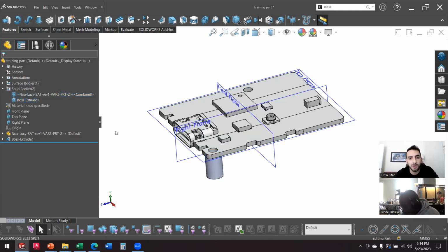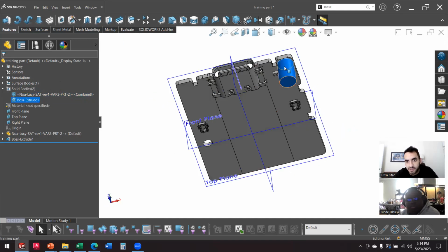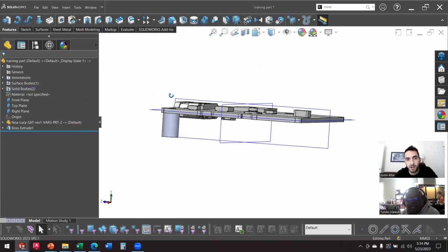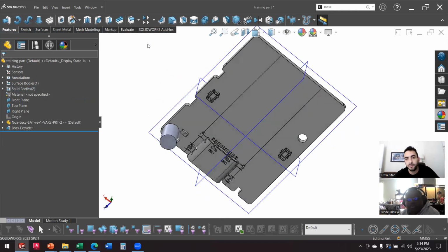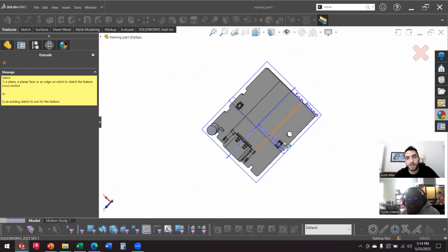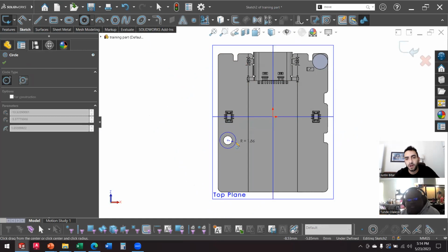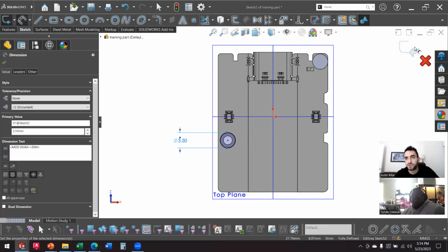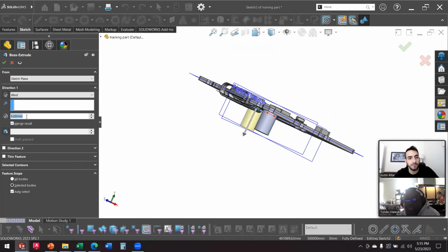But anyways, we've got this boss extrude that's its own thing. So when we select it, it just highlights that extrude that we just did. And now they're completely independent parts. And this opens up some new things. And we could just keep doing that actually. So we could come over here and do the same thing, and do a 3.5 millimeter screw boss, and then extrude it 5 millimeters, and we don't have to merge the results.